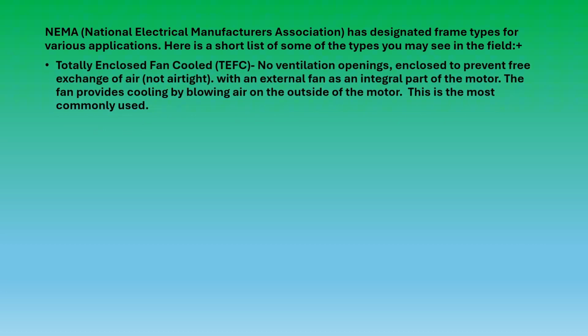Totally enclosed fan cooled. No ventilation openings, enclosed to prevent the free exchange of air, although they're not airtight, with an external fan as an integral part of the motor. The fan provides cooling by blowing air on the outside of the motor. This is the most commonly used.